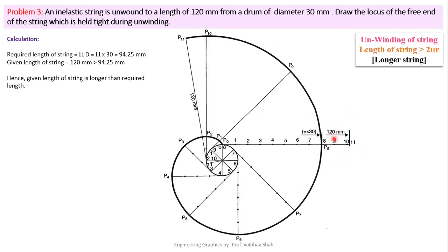That means we have to just simply locate all the points of this line onto this circle also. So how to locate these points? You have to simply take the dimension of 8 till 9 on your rounder, put your rounder at point 8, and you have to go in rightward direction because this is a dimensional pattern. So 4, 5, 6, 7, 8, that means 9 dimension must be on the anti-clockwise side.